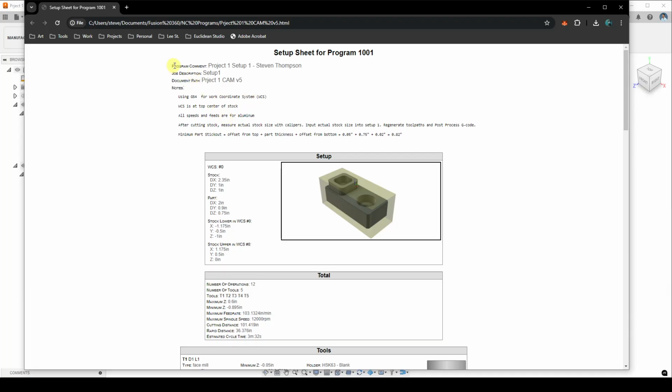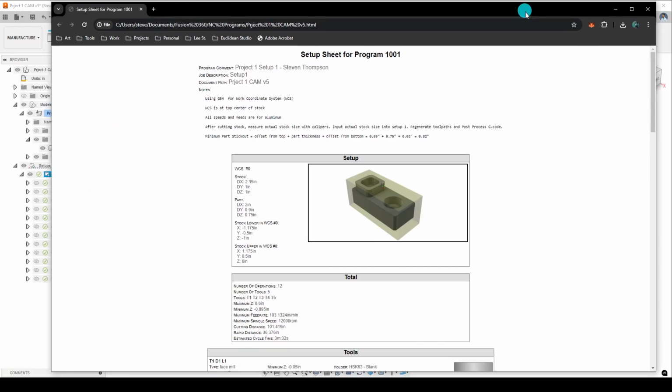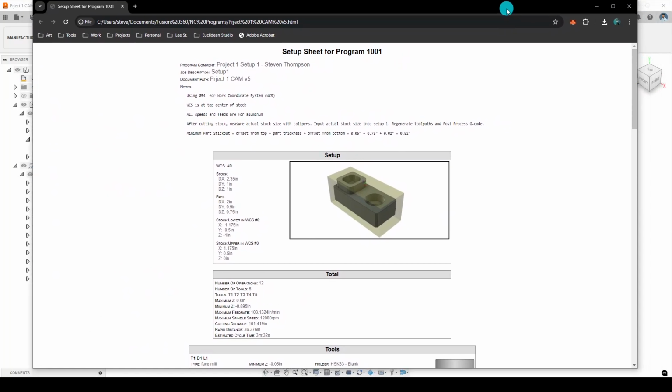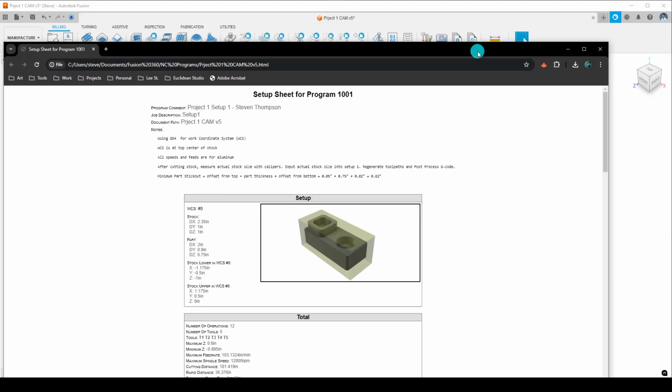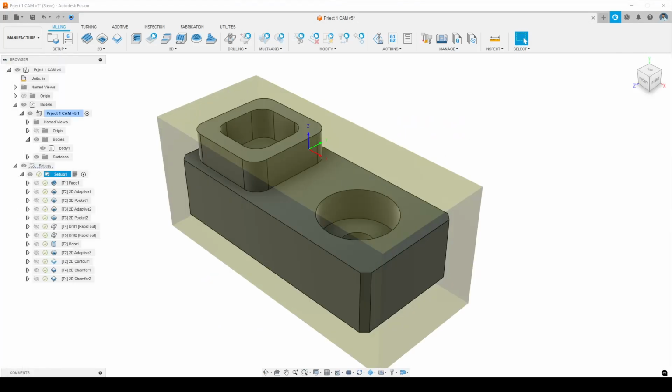part, or change a tool order, then your setup sheets aren't going to be valid anymore. So I'll make these right before I go to program, or right before I go to machine my part. And if you change anything, you need to make new ones. So they're only as accurate as they are current, I guess. Okay, so those are setup sheets, really important.